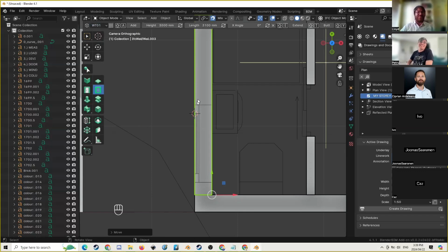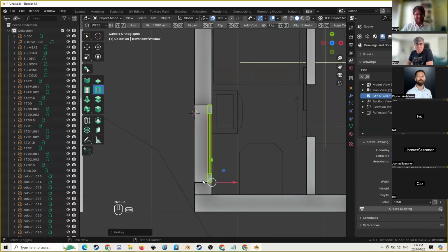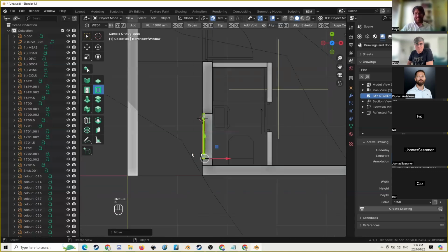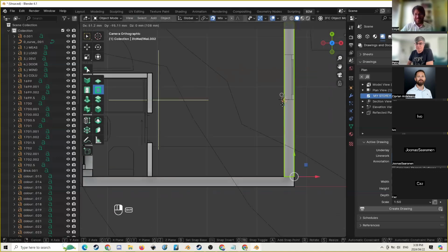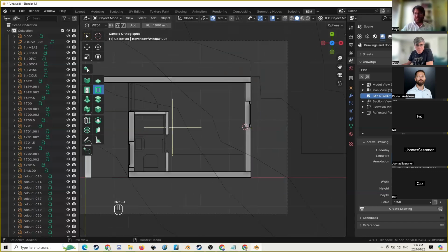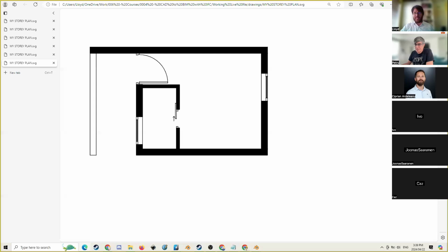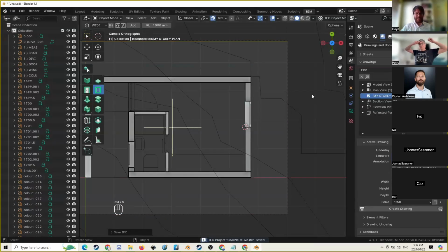Yeah. So window type 1, I'm going to press Shift A. There's the window type. Thankfully, it's exactly the same size. Press Shift G, bring it to the end here. And then again, snap it to that position, Shift A. It's in the correct position. So I'm just going to say activate and then print. And then I'm just going to save the IFC.